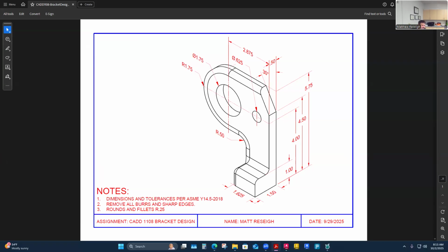Well, let's put that to practice now and start drawing this thing. So all I'm going to look at is in my front view, it's going to be the overall height here. This is shown as height, but I'm going to turn that into width. It's going to be 5 3/4 for the total part. And then if this is my top surface, that means this to that is going to be the height of this in my front view. So it's only going to be an inch and a half. Pretty skinny, an inch and a half high and 5 3/4 wide.